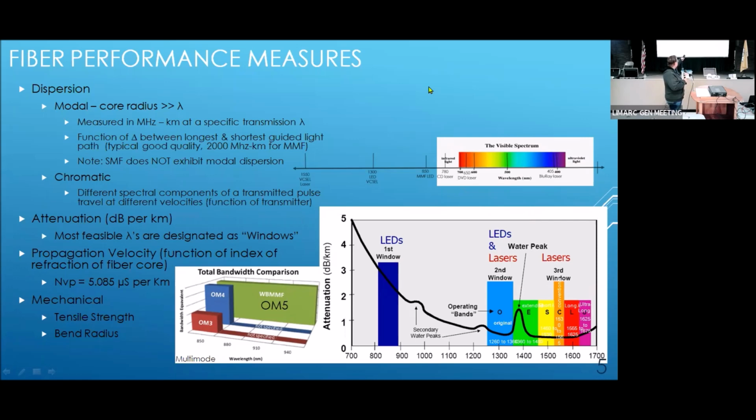Here we see that there's a water peak in which our attenuation in dB per kilometer is pretty high. This particular fiber that they took the sample of is probably not a really great piece of fiber. The best attenuation that it looks like we're getting is about 0.4 of a dB per kilometer. Imagine getting that on a coax, 0.4 of a dB for a kilometer's worth of coax. Most of us would be thrilled to death to see that. Of course, it doesn't happen.